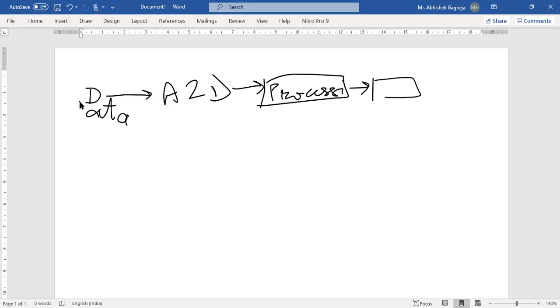And normally, this bit stream is met with a line code, right? Now, this particular line code is important in the sense that this line code contains the electrical representation of the data. And what we have studied in unit 4, or what we study in unit 4, is that beyond that electrical representation there is a possibility of overlapping a higher frequency, the carrier frequency, onto the data. And essentially what that does is that it prepares the data for long range communication as modulation does.